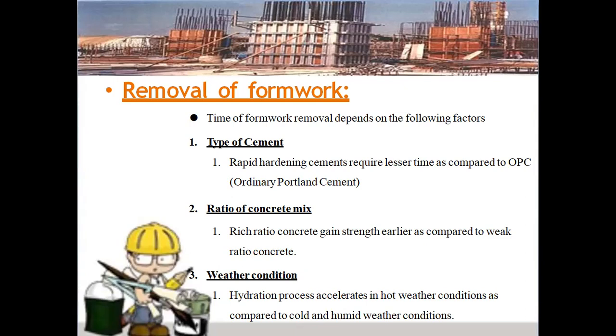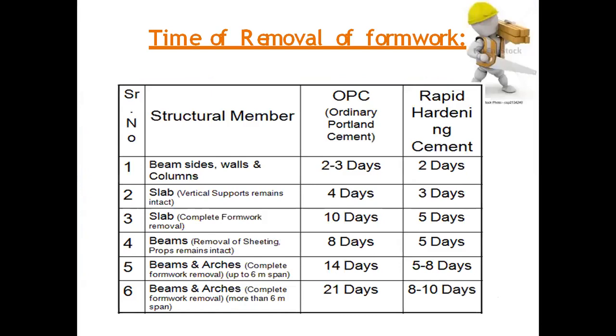The ratio of concrete mix: rich ratio concrete gains strength earlier as compared to weak ratio concrete. The weather conditions: the hydration process accelerates in hot weather conditions as compared to cold and humid weather conditions. Time of removal of formwork.